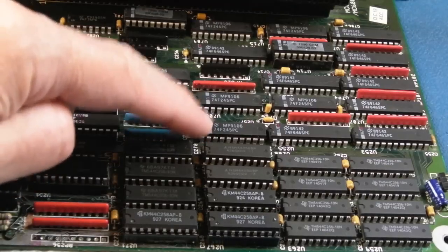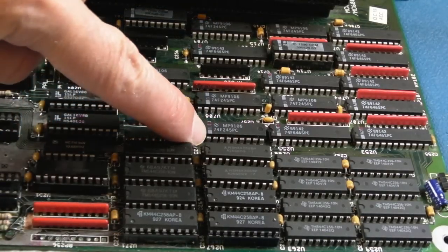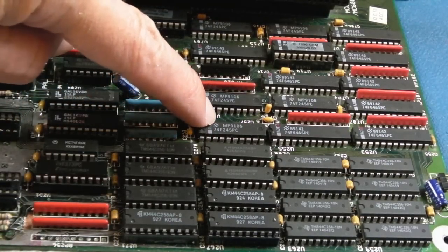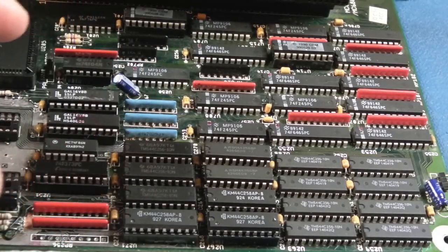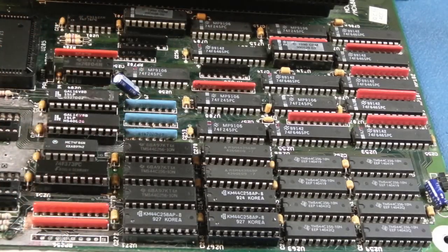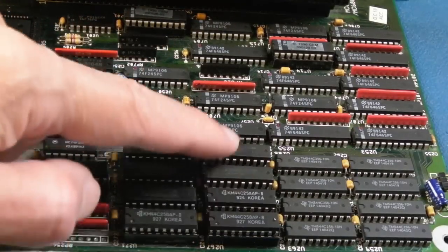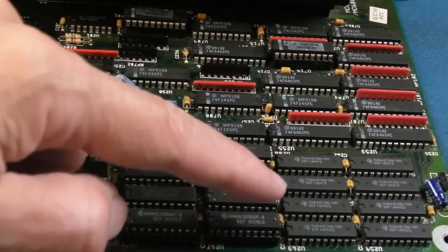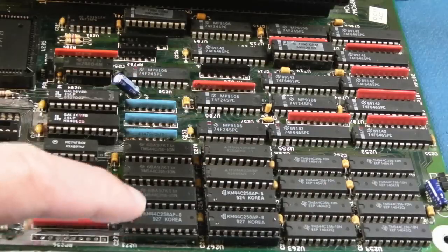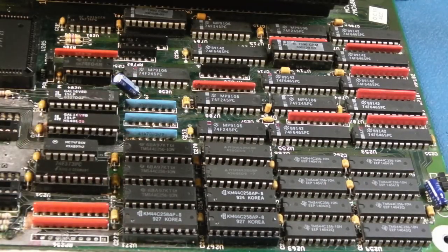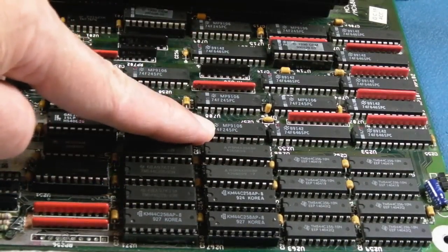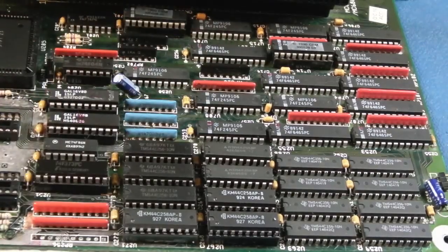This is the one I've been probing. The weird signal is on pin 2 here. Its input came from pin 18, which comes from pin 1, and we're looking at that data bit, D16, I think, because D0 to D15 are on these pairs here and the upper ones are here. We do know it's this data bit according to the schematics. So anyway, let me get that off. I'm just going to use some hot air. We'll socket it up, I've got a replacement, and we'll see if that solves that data bit.